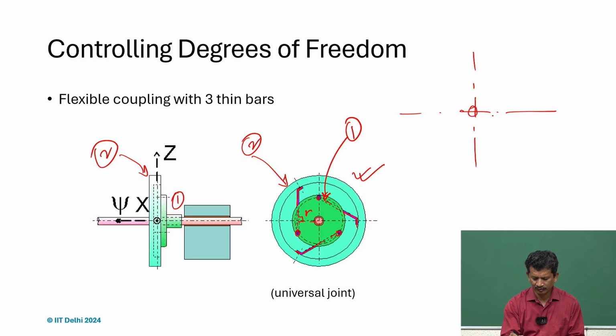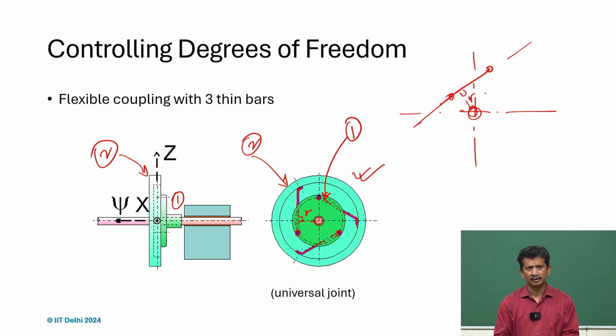If you have this, it can be any axis. It can be from here to here, but what is important is that when we drop the perpendicular, there should always be an offset, it should be away, because that is what provides the required torsion to move it, and the stiffness of this member is important in that case.